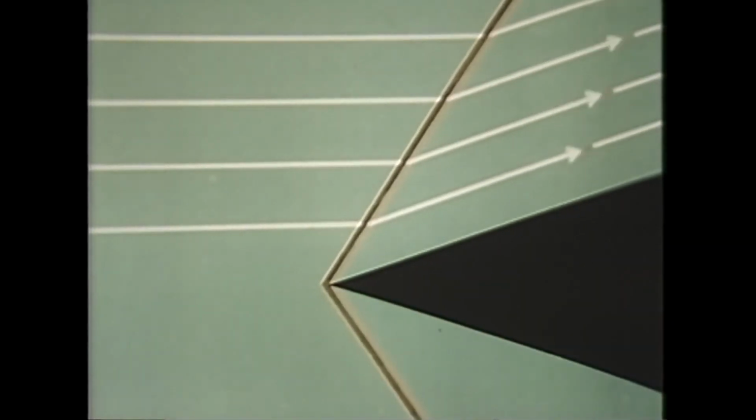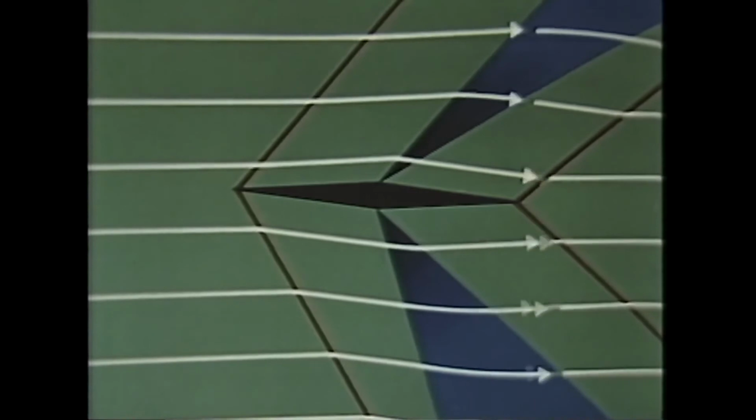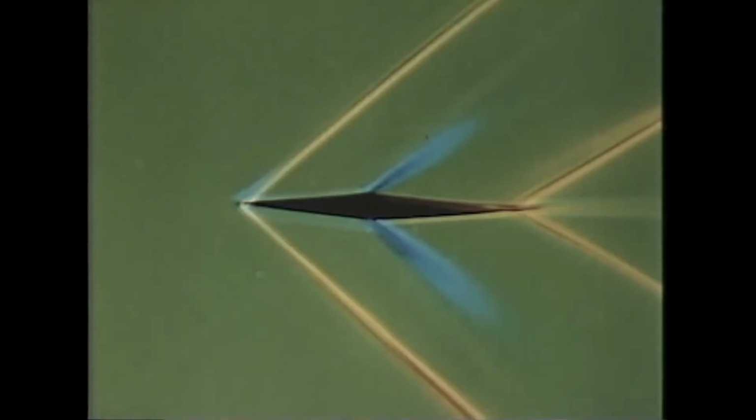The corner may be at the leading edge of a wing. So supersonic aircraft can use sharp corners, as for instance, the double wedge wing section. The changes of pressure caused by the shock wave and blue areas give the wing its lift. Here's a wind tunnel picture at nearly twice the speed of sound. Another shape, formed by two arcs of circles, is the biconvex, which, like the double wedge, has sharply pointed front and rear edges.